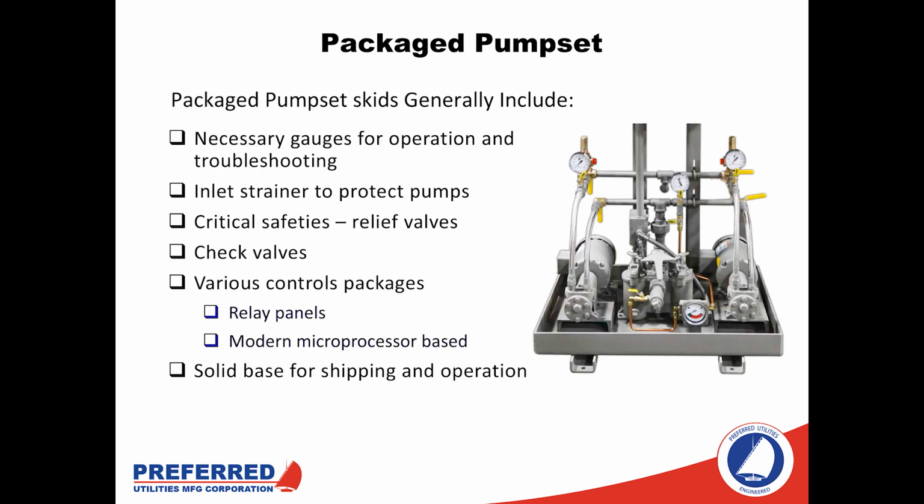Now, the package pump set offers a lot of advantages, and this is going to be typically how we see these in the field now. There are still some applications where we'll see the transfer equipment being designed piecemeal, and the contractor will purchase each part, such as the strainers, the gauges, all of those different things. But the advantage of having one manufacturer or sole source of supply for the skid itself is that necessary safeties, such as the relief valve that we just talked about, all of the gauges, the strainers, things like that, are all going to be sized right from the get-go properly.